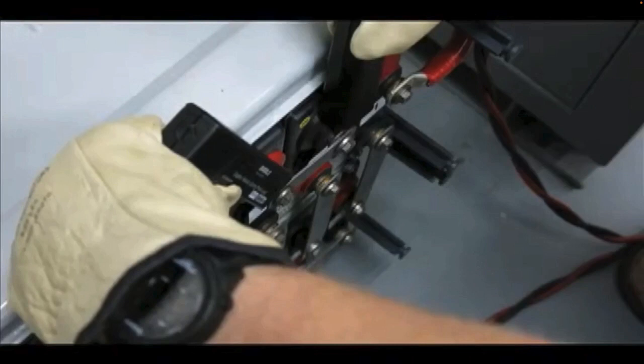All right, now let's look at an optional test method that will not only capture cell voltage, but in the process of this test method, we will also capture internal cell impedances and strap resistance values. Now, the test that we're going to talk about as the optional pre-test is the battery impedance test.